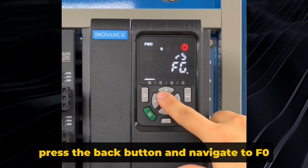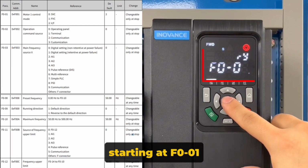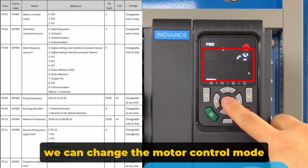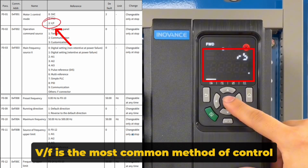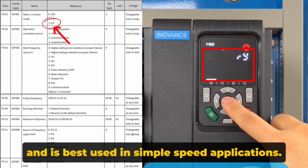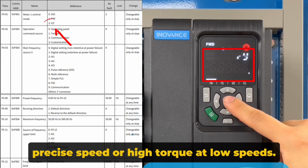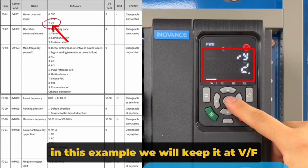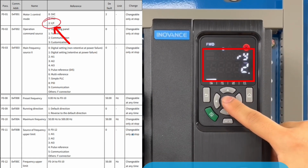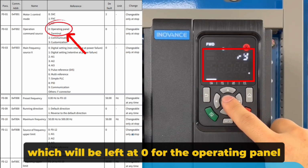Press the back button and navigate to F0. Starting at F0-01, we can change the motor control mode. V/F is the most common method of control and is best used in simple speed applications. It is ideal for applications that do not require precise speed or high torque at low speeds. In this example, we will keep it at V/F. F0-02 is used to change the command source, which will be left at 0 for the operating panel.